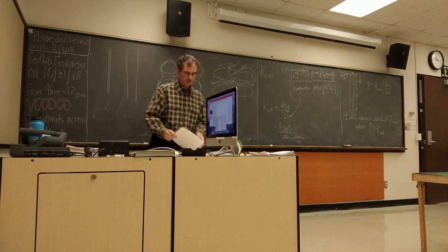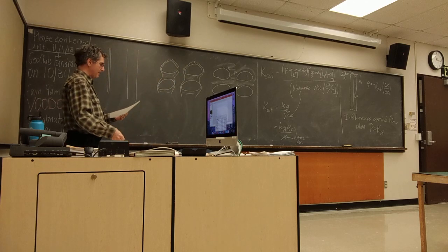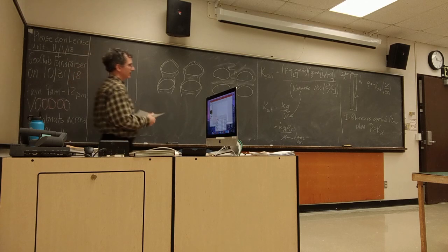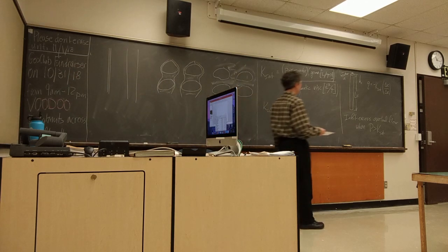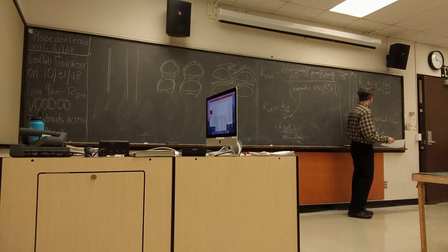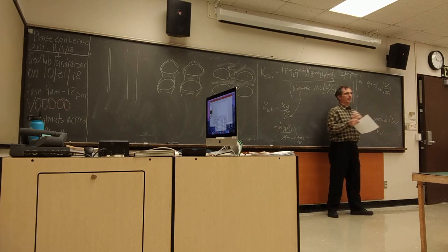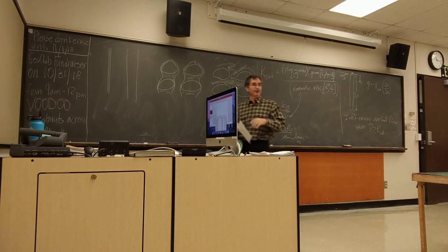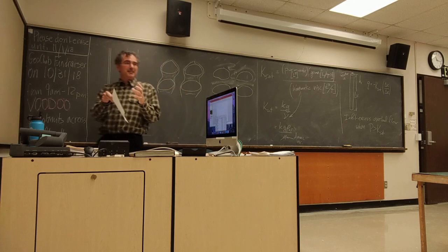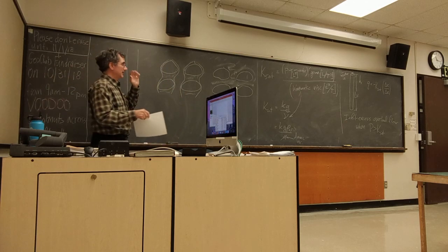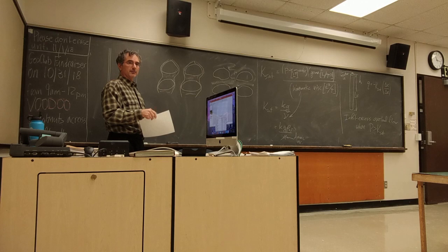Interesting facts. So, in basic summary, we're going to generally get infiltration excess overland flow when precipitation rate exceeds the saturated hydraulic conductivity. The details of what happens before that hydraulic conductivity reaches the saturated value are actually pretty interesting. That means really complicated. So